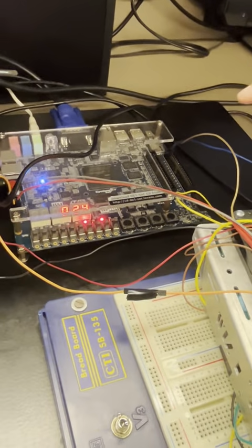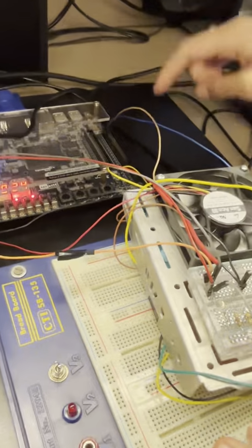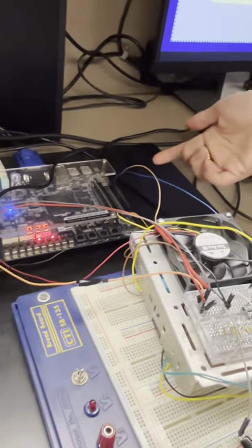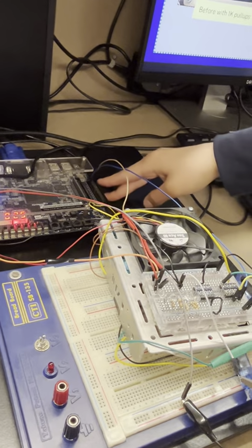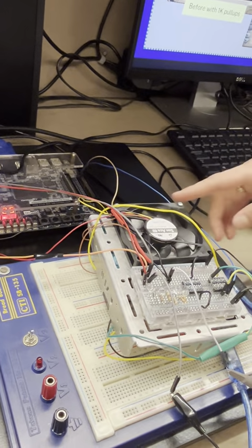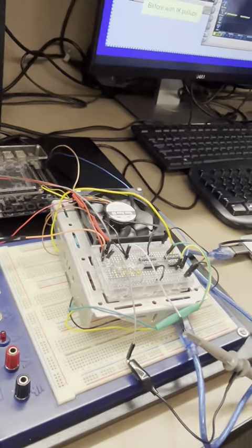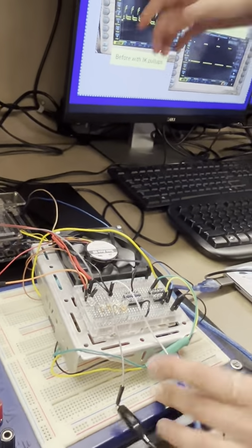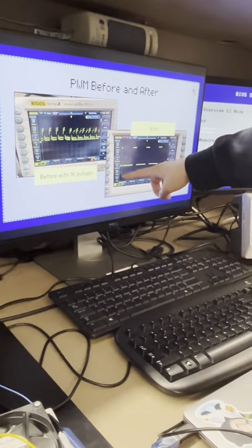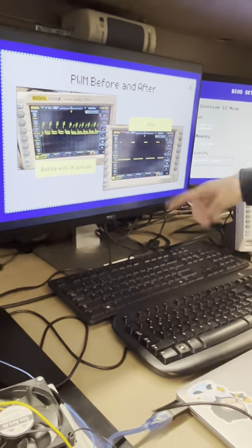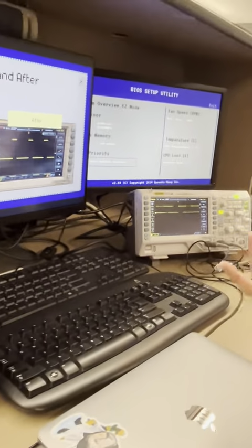And then once we have a temperature command, we convert that to a duty cycle, which controls the speed of the fan through something called pulse width modulation, which is through these two wires. And we weren't able to drive it properly at 5 volts because with our level shifter, we were having a lot of issues with ringing, so we just got rid of it, and we're getting a clean square wave, but we are losing around 16% power.